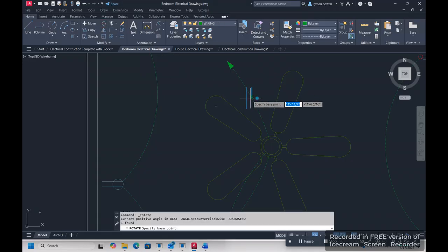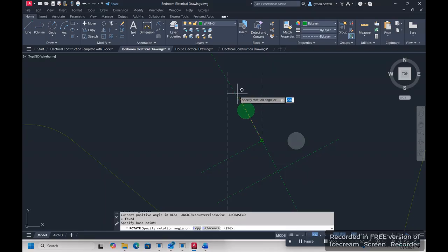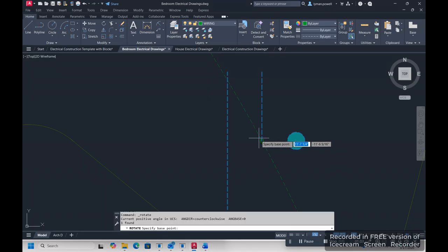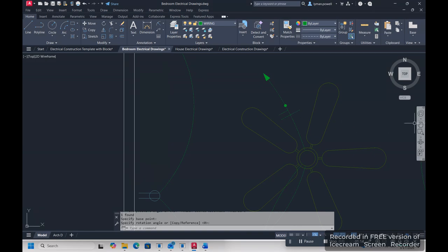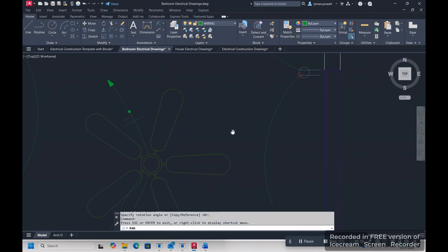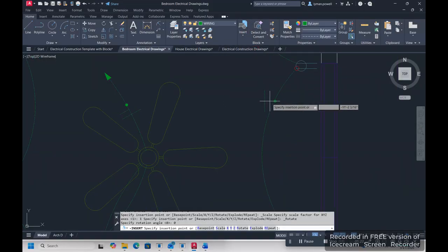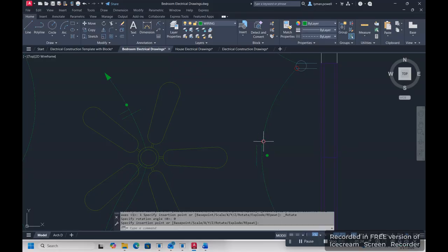If we do from our center point here, like we did in that other drawing, and get it fairly close to where the center is in there, and we can zoom in a little bit so we can see. It didn't work, so rotate it from the center point, rotate it around until we get about where we want it to be, and then click, and that will be where we add that. So we should have a block for these. So if you just hit insert, click on your conductor wiring and go to where you find the middle point of your arc.